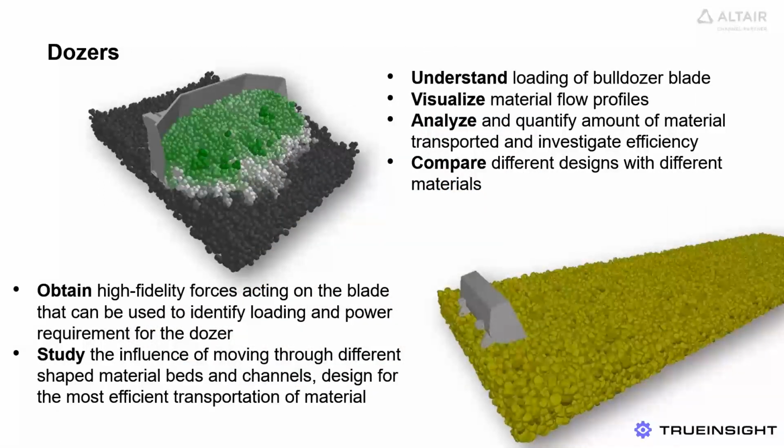Much like the excavator example, EDEM can be used in a similar manner to analyze and understand the loading on dozer blades. You can easily compare different designs by replacing or adapting geometries to attain high fidelity forces on the blade, which can then be used to calculate power requirements.